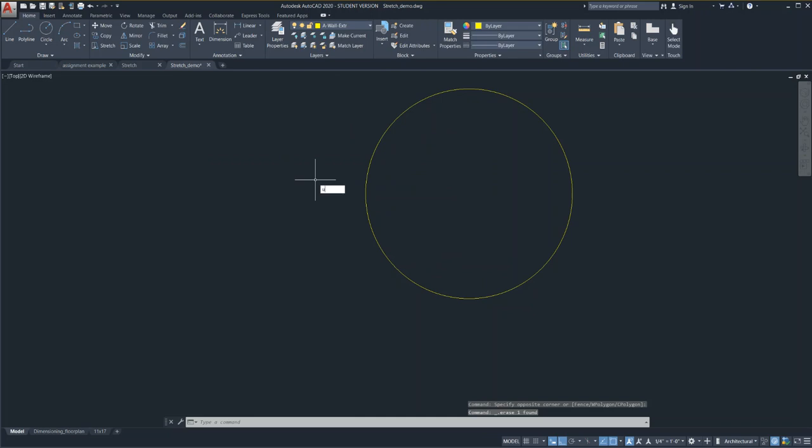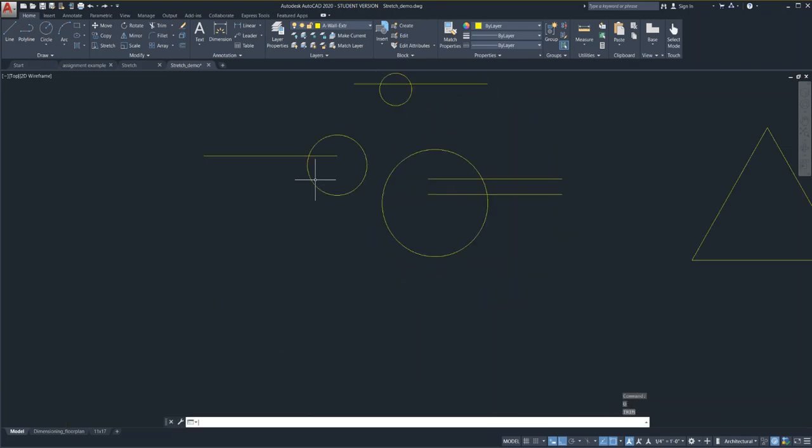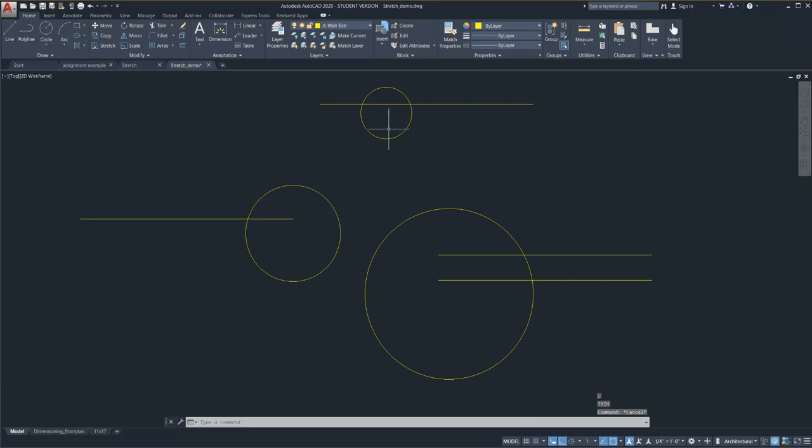Okay? Undo, enter, enter, enter again, trim, TR, enter, enter. So we can trim, click, trim, click, trim, click. Ooh, I can't trim those because they're just line pieces, right? Again, they're not going over the boundary. They're just little line segments, so I'm going to delete those, okay?